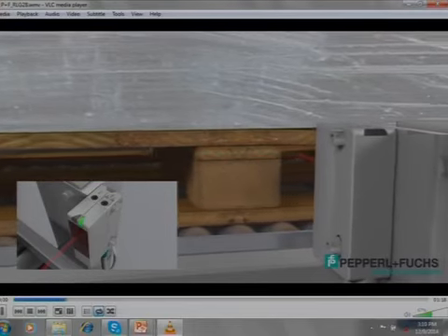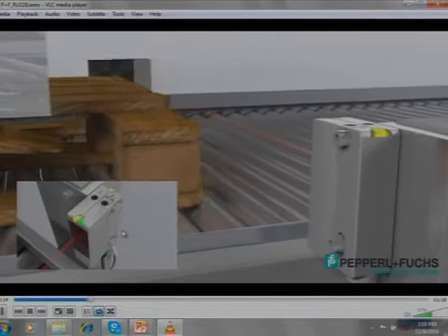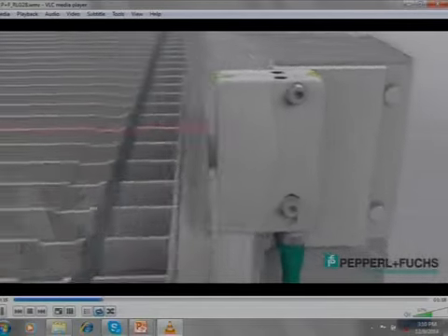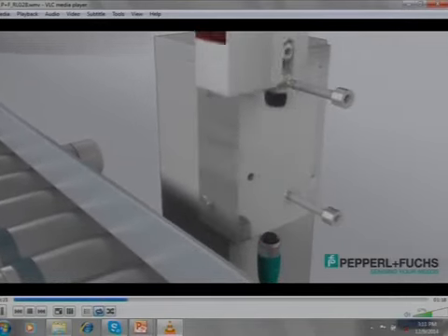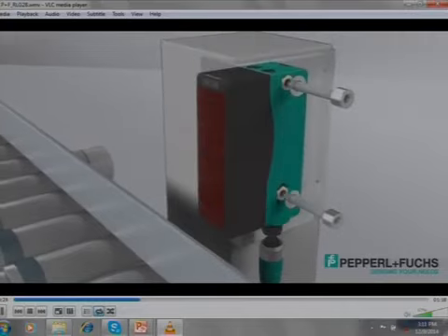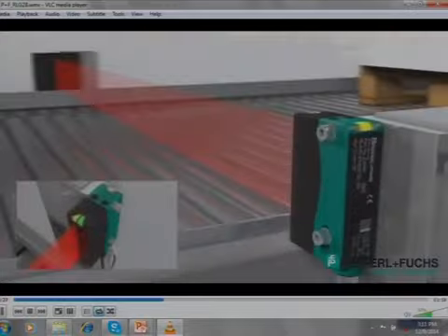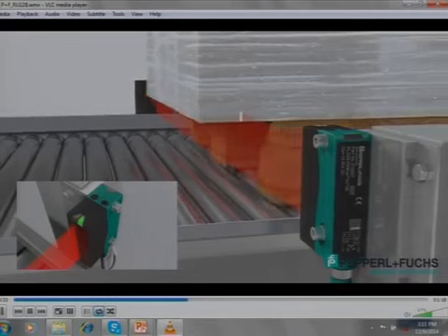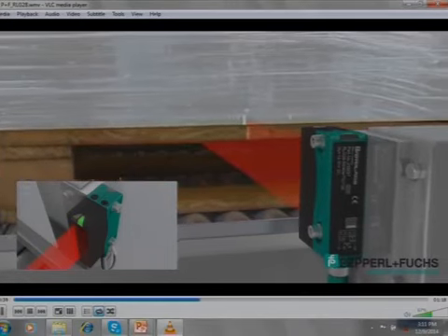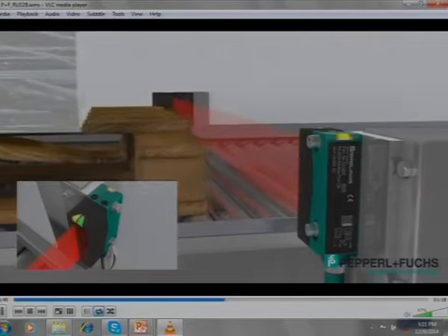Now, these are different types of retroreflective sensors. There is a fine beam retroreflective sensor, that means only a fine beam is going and hitting the reflector and coming back. It does have a drawback because if the components are not uniform, like what's happening here. So, for that there is a retroreflective sensor which has a band of beam. That means there are multiple transmitters and multiple receivers inside it. So, it forms like a band. The band goes and gets reflected back. So, even if the target is not uniform, it will still count 1. That means you will still get a proper output.